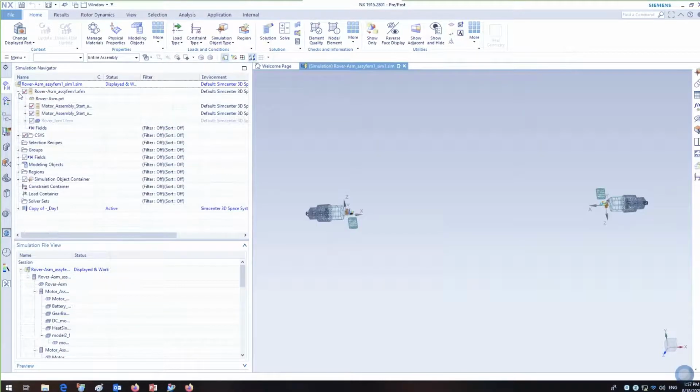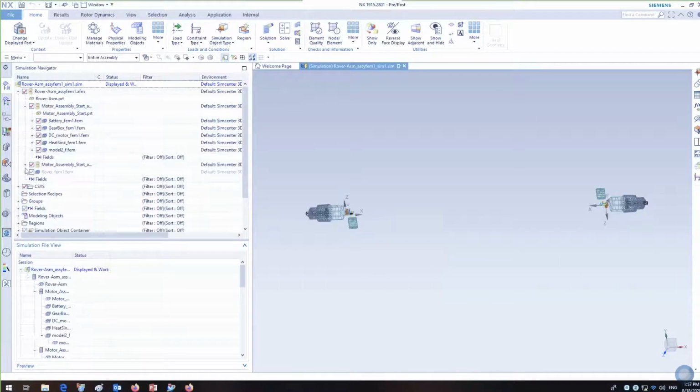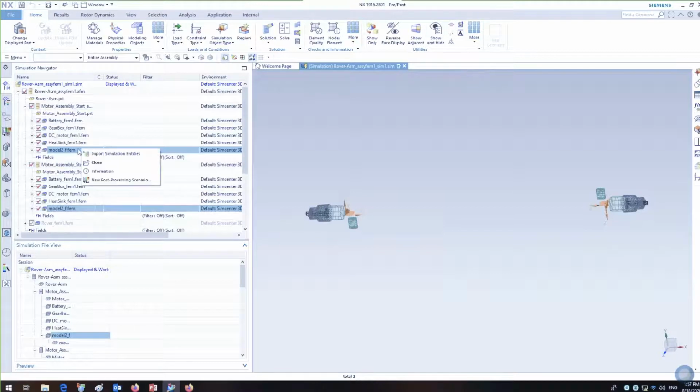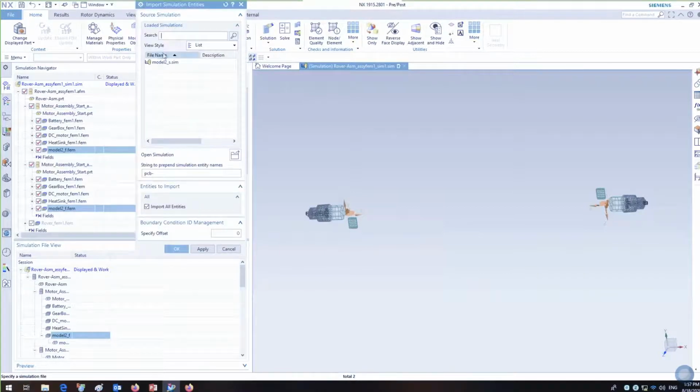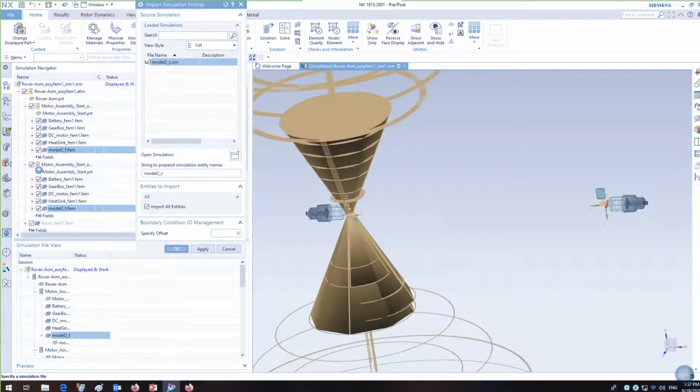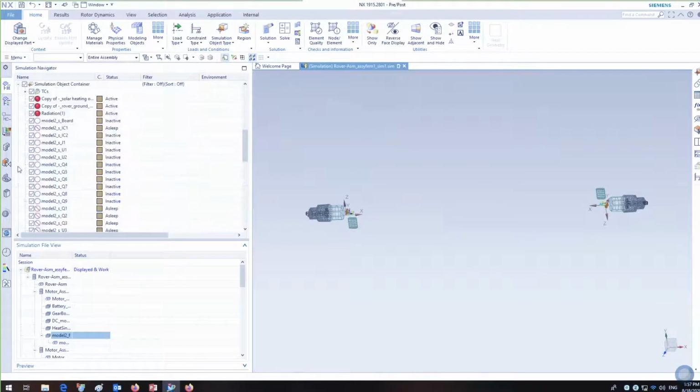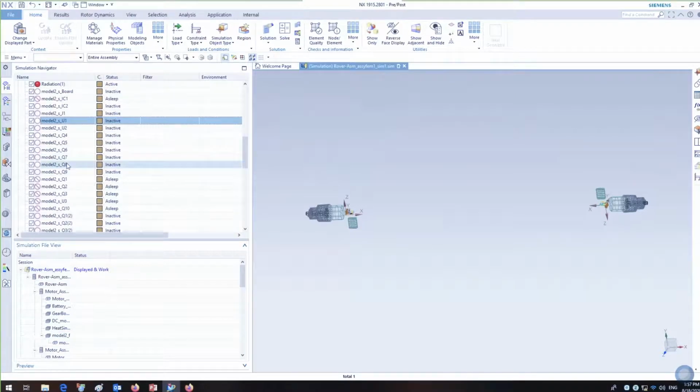model. Since this is a subassembly that is repeated twice in the model, the PCB board is instanced twice automatically for us. We don't need to go and place each one individually. Now we can go into our simulation and import our boundary conditions for the PCB components, as well as the different boundary conditions.